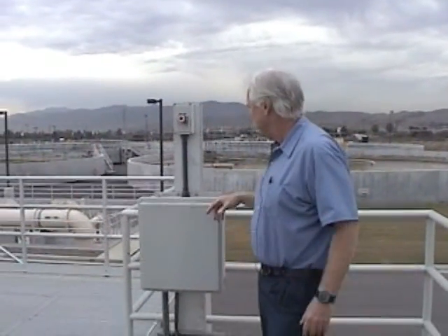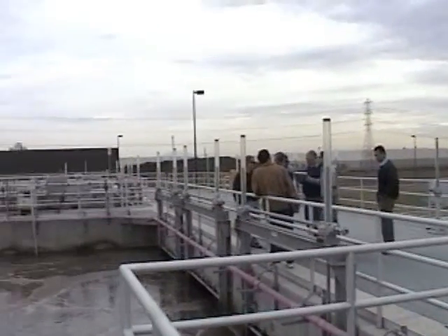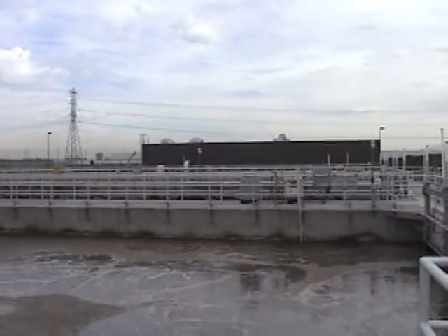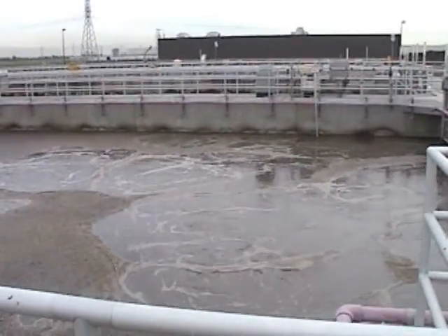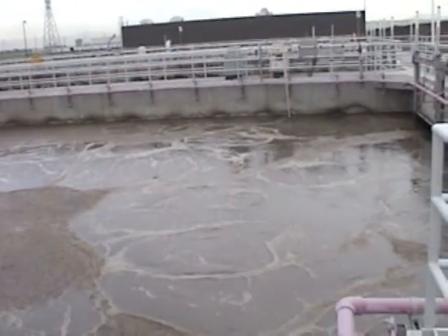And the pumps that do that are called mixed liquor return pumps. This is the E-stop for the MLR pump, MLR for short, mixed liquor return pump. You can turn these off and on from the SCADA system when they're in remote, or if they're in local, you'll have to go to Power Center 2 to turn them off and on. Typically, we like to leave them in remote. That way you can turn them off and on from the computer system.